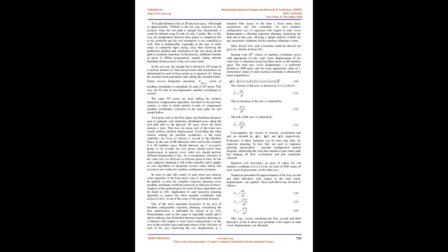In order to determine appropriate machine coordinates for the given pose, the inverse kinematics algorithm based on the Paden-Kahan subproblems could be applied. Details of the algorithmic approach of the generalized form of these subproblems are given in Dimovski et al. [10]. Using this approach, 8 solutions of machine coordinates are usually determined, so a trajectory planning algorithm is used to choose the most optimal one. For the 6R industrial robot used in this research, 6 machine coordinates respective to 6 rotational axes are obtained.